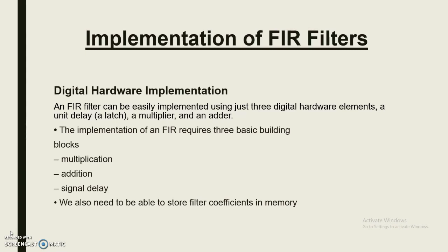Adder. Signal addition is a very basic DSP function. In an FIR filter, additions are required in combination with multiplications. Hence, DSP microprocessors feature multiply accumulate units. Adders generally operate with just 2 inputs at a time. Signal delay.